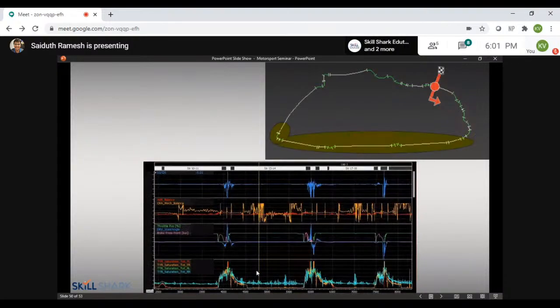You can maybe have a look at the recorded session a little later to try to understand the graphs. I'm just showing this so you can have a look at it now. A lot of changes in understeer and oversteer. You have big issues in balance here. And these three zones are basically these three chicane areas here and the final turn. So you see, whenever you're on a straight or in a high speed corner, you don't have a lot of problems. When you get to these slow speed twitchy sections, right, your car starts twitching.